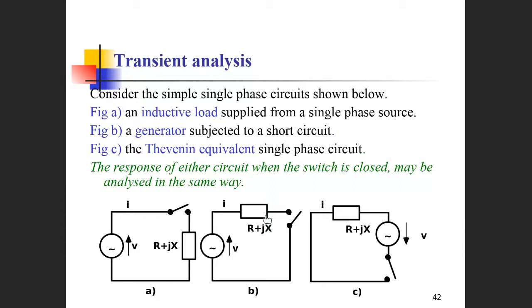The transient current is usually very big, which damages the systems. So to keep the systems safe, we have to design systems by taking the transient current issues into consideration. We should install some protective devices so that the system can be protected against short circuits and transient big currents.